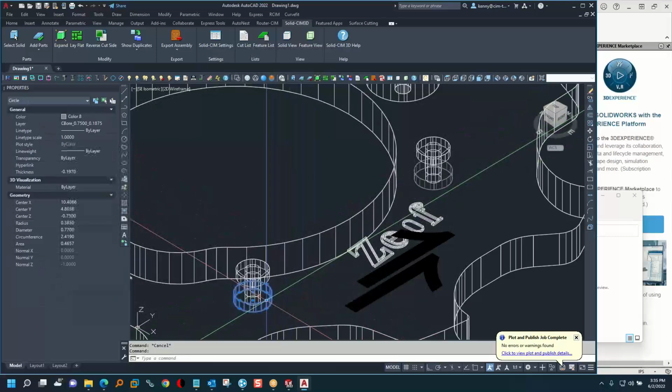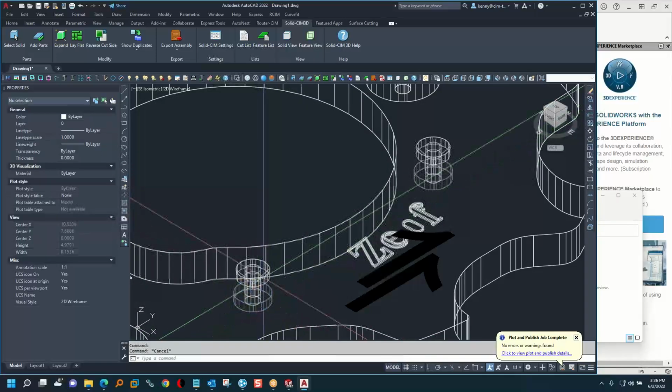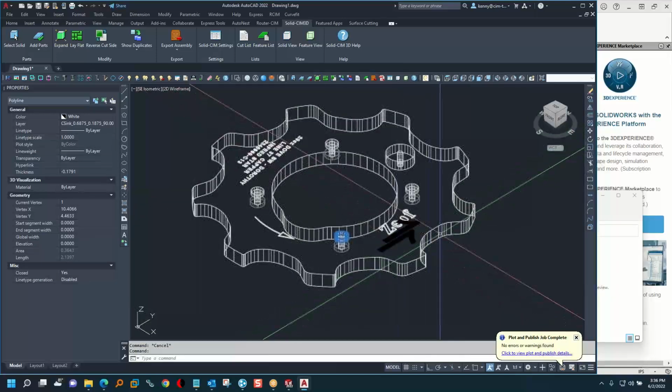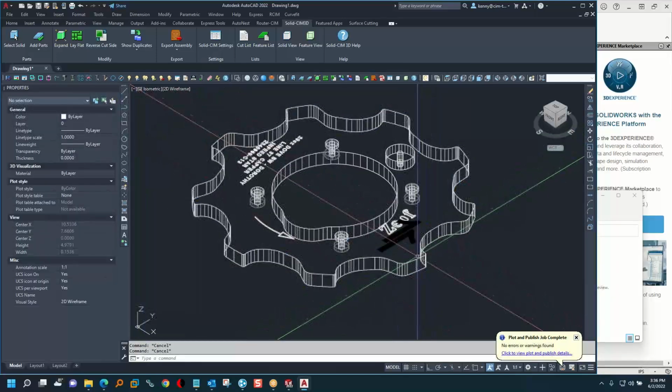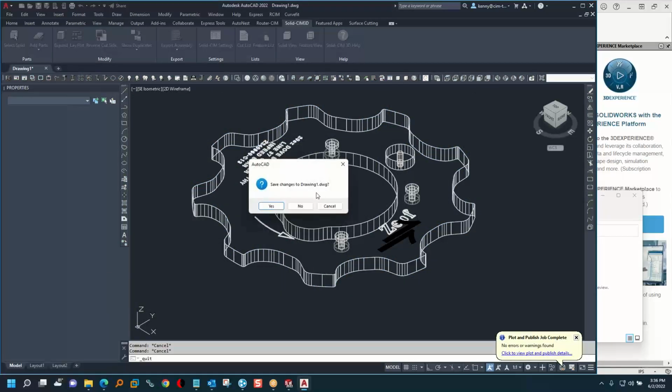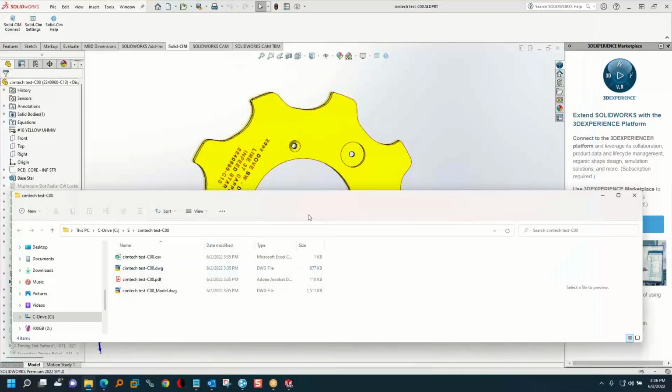And there's going to be some counter bores. They're going to be on the bottom on the layer called C-bore bottom when it gets exported. And then layer outside here. Right here's layer outside. So it just exported all that.